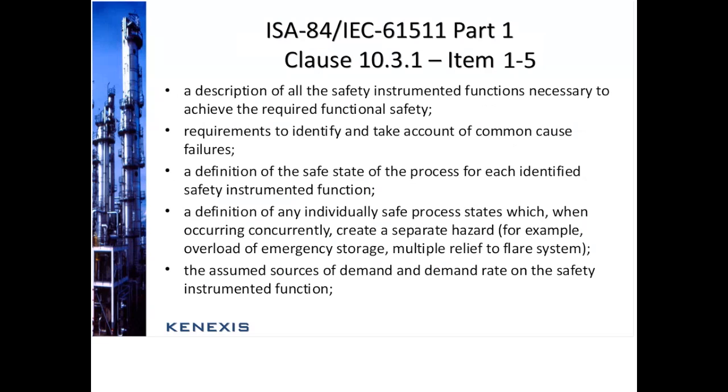A definition of the safe state of the process for each defined safety instrumented function. The safety instrumented function is going to take an action to put the process into a safe state. In our fired heater, it's going to close the gas valves. So that definition needs to be clear and concise.